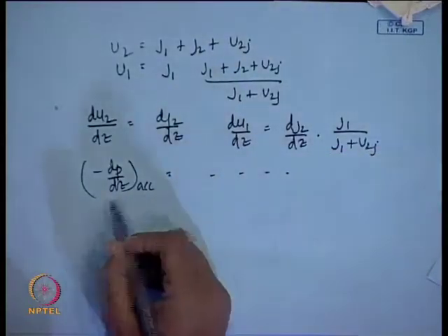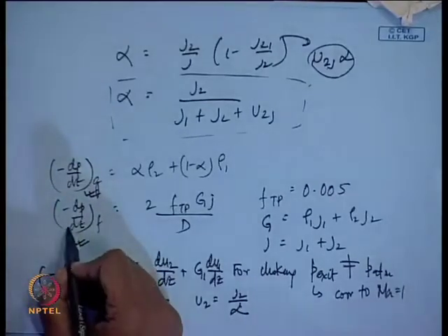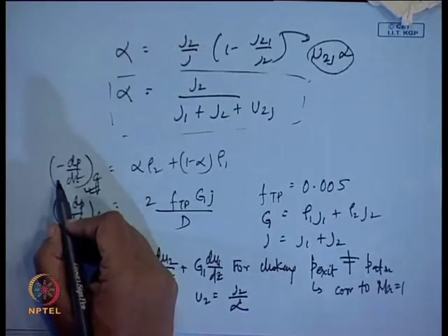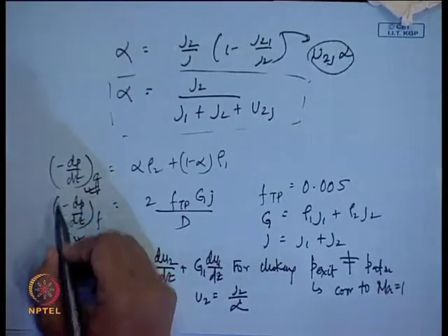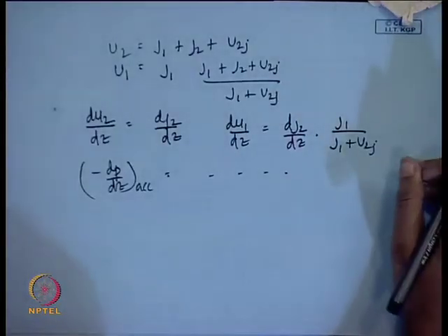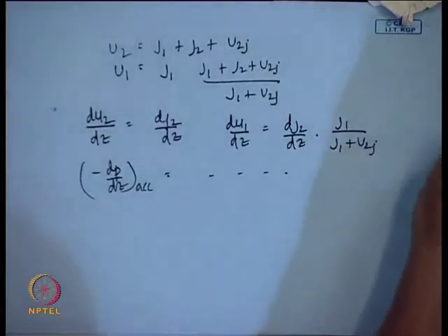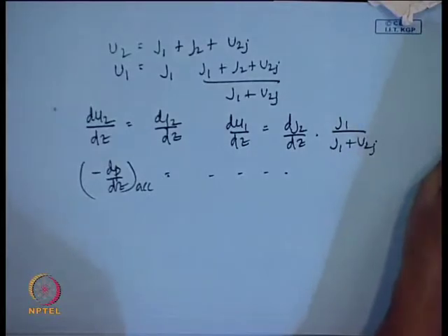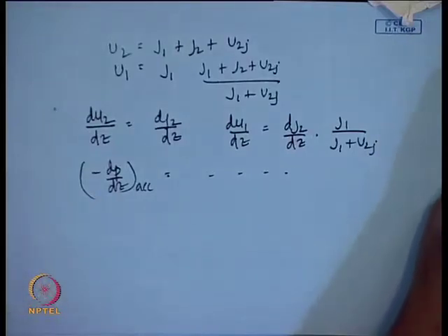Then we can add up this acceleration expression, frictional expression, and gravitational expression and get the expression of the total pressure gradient. Once we get the expression of the total pressure gradient, then from there we can find out the condition of choking, we can find out the value of Ma, and verify that Ma is not equal to 1, it is less than 1. When it is less than 1 we can assume that the exit pressure is equal to the atmospheric pressure, and accordingly we can find out dp/dz, and for 3 meters length we can find out P entry when P exit is atmospheric pressure.